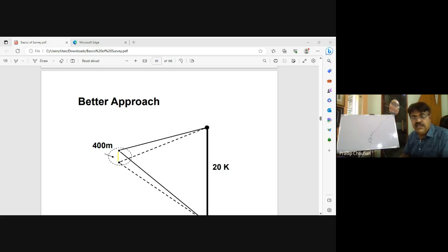Normally, again, the same way, you are having levels reduced. So what is the GTS benchmark? Worldwide, the GTS benchmark has been reduced from mean sea level. And from the GTS benchmark, there is a permanent benchmark in the country. There are so many police stations, post offices, railway stations that have a permanent benchmark. From the permanent benchmark, we are reducing to a temporary benchmark, and this we might be using.